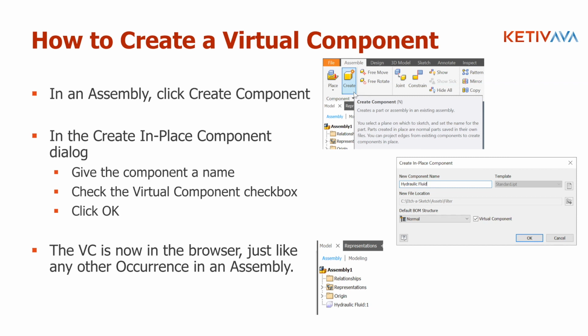Virtual components have been there since the bill of materials capability was created for Inventor, and that did happen in Inventor 10. So they've always been there all along. This is why I say most people don't even know that they exist. They're not as well documented as I would personally like, and the use cases for them aren't as well known as I would like, but they can be very, very handy.